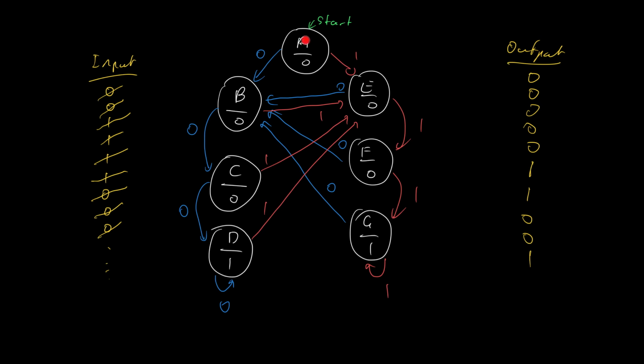In the Verilog code, we need some way of storing the current state, and we use flip-flops for that. And that means we have to associate some sort of a binary number with each state. But that's in principle easy to do. We can just make up a simple ordering. We have got 7 states here, so 3 bits is enough. I can say that this is 000, 001, 010, 011, 100, 101, and 110. That's pretty much it. A finite state machine is as simple as moving a red shoe around the state diagram.